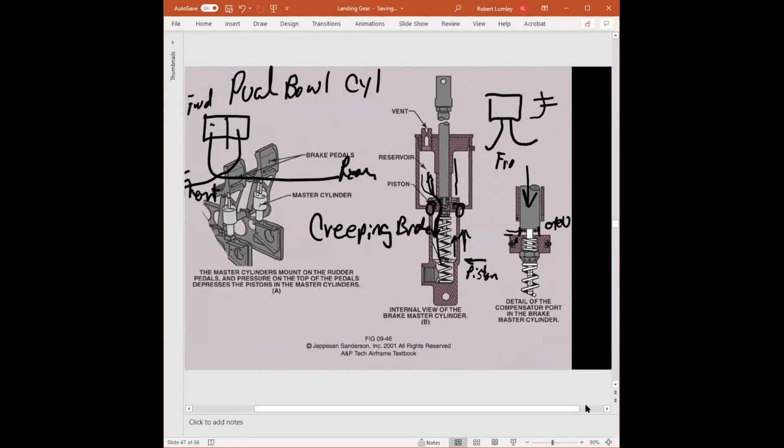Okay. And what that means is when you first put on the brake pedal, it feels hard, but as we maintain the pressure, it slowly goes down. Now, the book calls that a fading brake, but fading brakes to me is when the brakes are hot. This is what I know as creeping brakes. They're creeping down. Okay. So I like the answer.